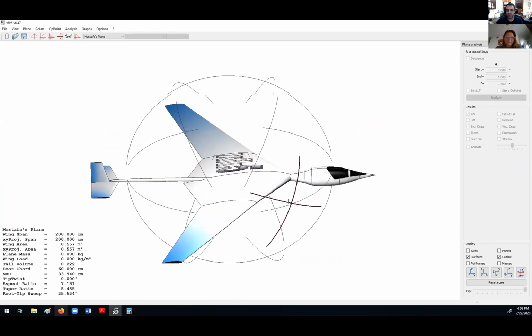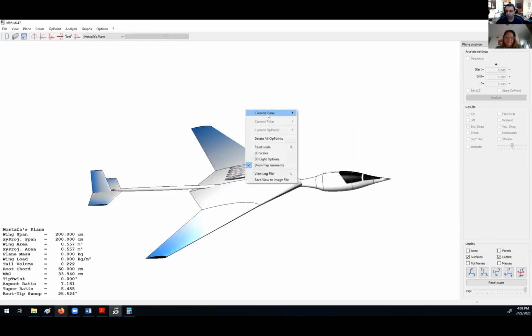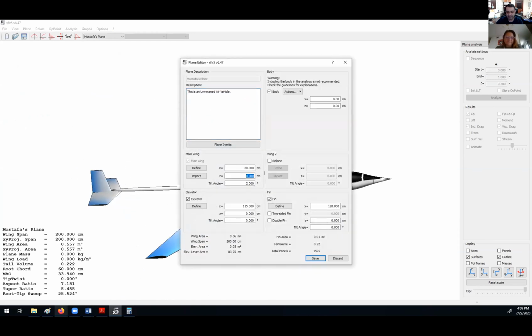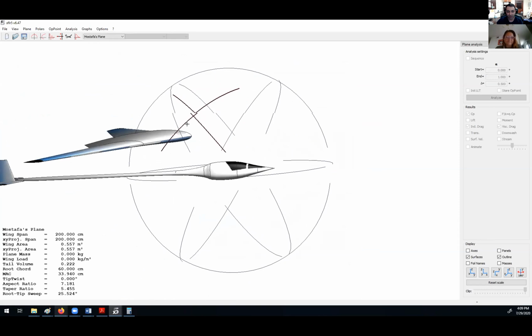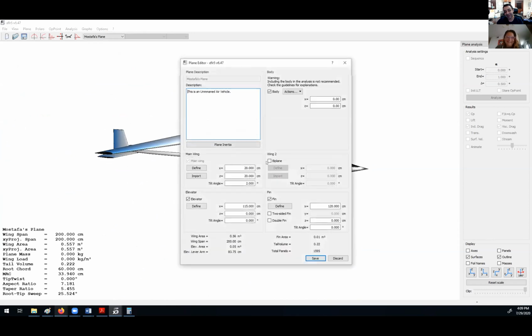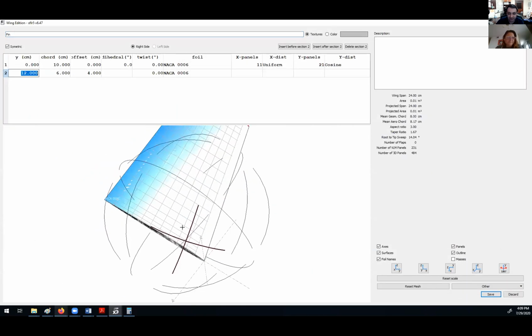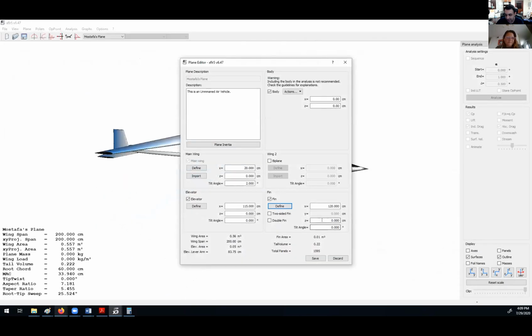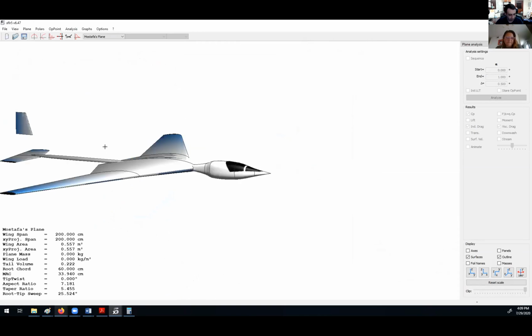Sometimes you want to make your wing higher. This is the Z here. This is 0. If I make it 20, the wing goes up. If you want to go back, I put Z 0. Now you want to have a T-shaped tail. You want to make this one at the top. If I go here, this is 12, the distance from here is 12. So if I make the Z 12 and press save, oh no, sorry.